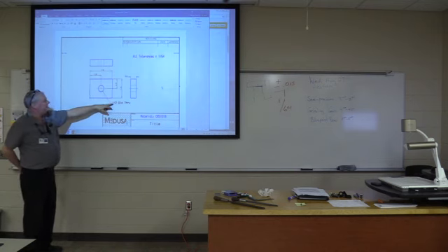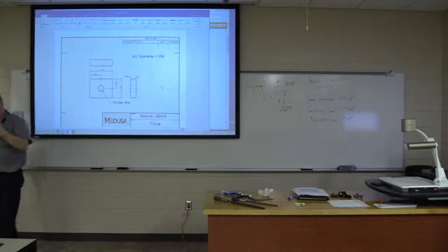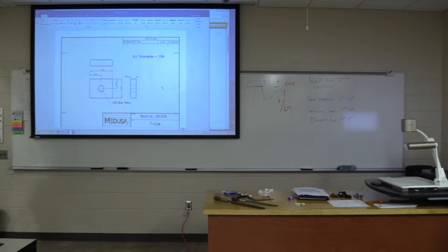And then we're going to take it to the drill press. We're going to do what's called center drilling. And then we're going to do a pilot drill, or a step drill. And then we're going to go with a 1/2 inch diameter drill. In steel, this is not like wood anymore. Steel is now much harder to machine.